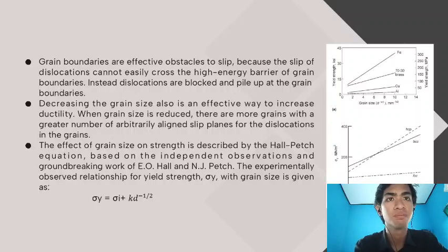Smaller grains in a polycrystalline material also mean that a greater percentage of the material consists of grain boundaries for strengthening. The exception is when grain boundaries become weakened due to environmental fracture or impurities or the precipitation of undesirable compounds or phases.